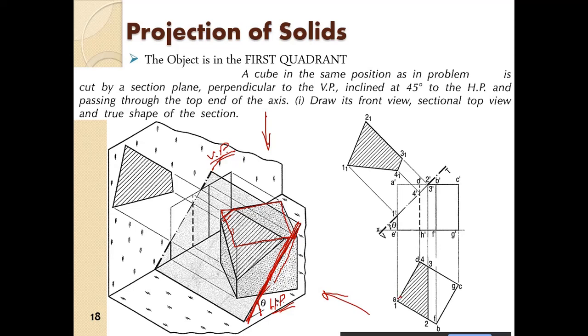Okay, so after drawing the cube, you first project the projectors for the points of the cube. And you draw the cube first. So this is the second step. So this is FB, and this is DH, which is hidden here, so dotted. So then you draw the cube. So first the top view of the cube, then the front view of the cube, projecting up.